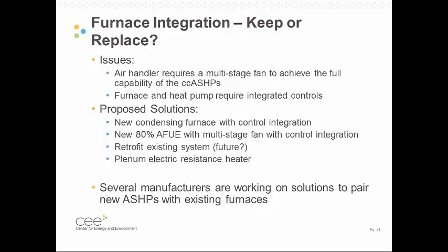The first option was just to go for it, install the best furnace they had, brand new, with the new heat pump. And that really gives you the best of all worlds in terms of performance. You get that brand new air handler that works really well. You get the totally integrated controls, all the options you can do, the multi-stage fan, all those things. And it also gives you a condensing furnace. When the furnace does have to run, you have the 90% furnace.